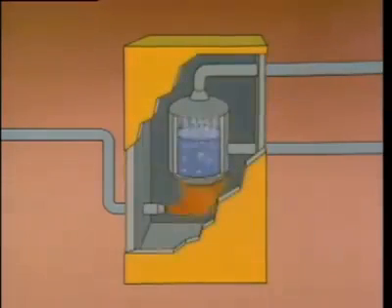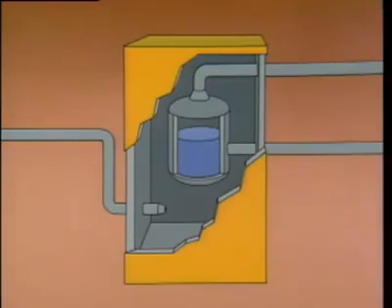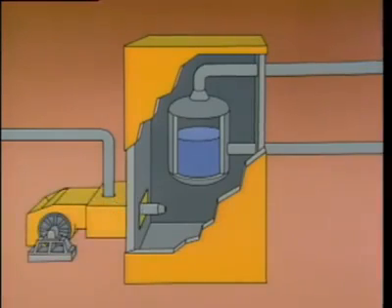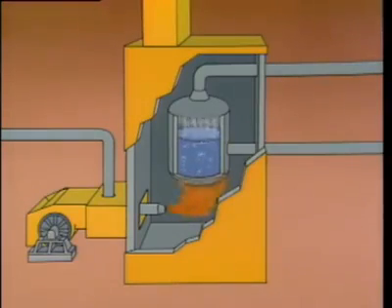This boiler can be modified further to make it more efficient. By adding an insulated casing, we can minimize the heat loss, but this creates another problem. The flame goes out because the casing cuts off the source of air. To correct this, we'll add a fan to supply air to the boiler and an outlet to remove combustion gases. Although this design is still greatly simplified, now we at least have a boiler that provides a constant supply of steam efficiently. In this topic, we saw the basic requirements for steam production and combustion. We also put together a simple boiler that operates to meet these requirements and produce steam.